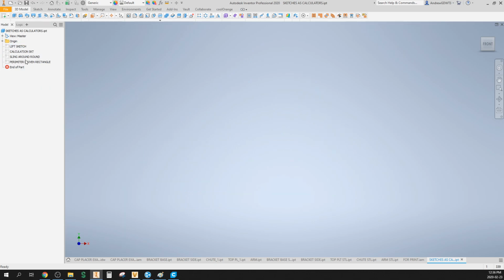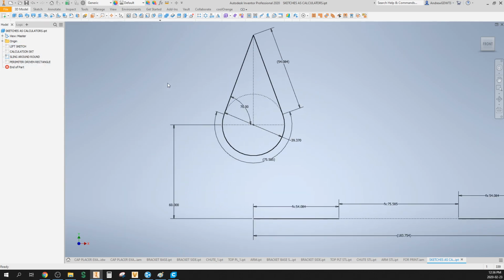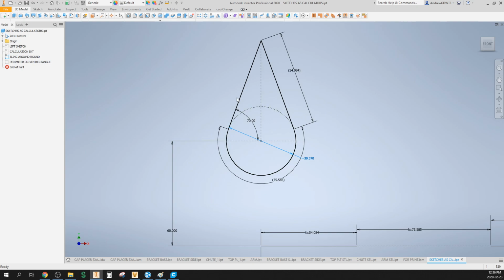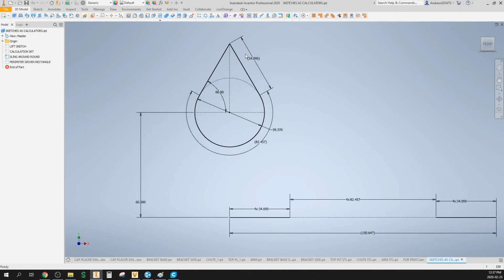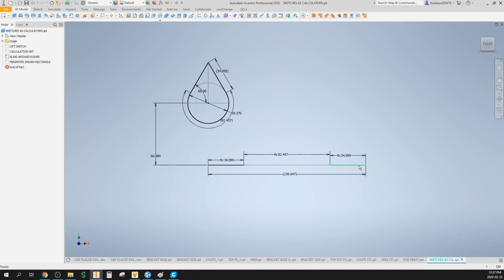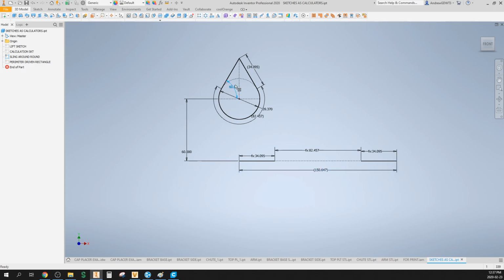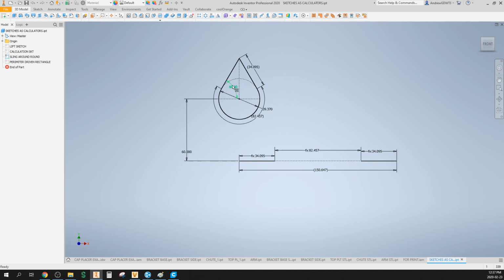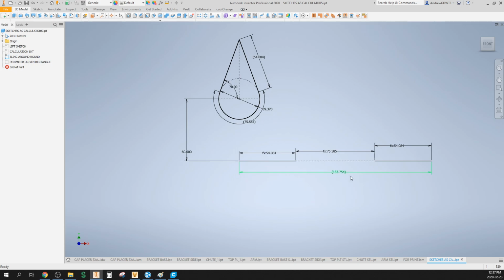That's the first example. The second example is another lifting one. In this case, I have a round object. It's 1 meter in diameter, and I want my sling angle, let's say instead of 70, I say I want it 60 degrees from horizontal. By making these lines tangent to that circle, so I have 2 lines and 1 arc, I can grab the line lengths and that arc length and add them up in a straight line down here, and I can get a resultant sling length that I need to make that happen. And if the diameter or the angle changes, let me try 70 here instead, it'll show me what my updated sling length needs to be.